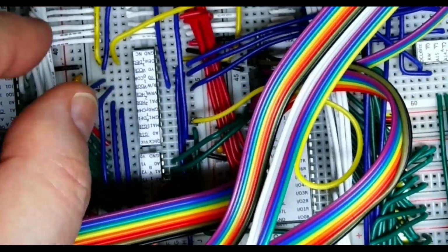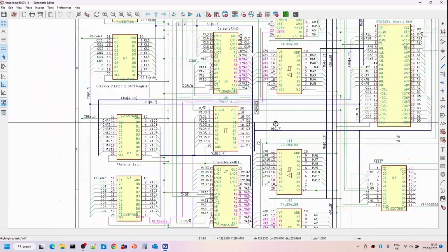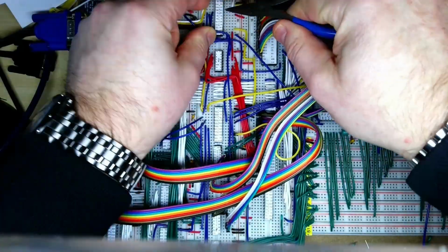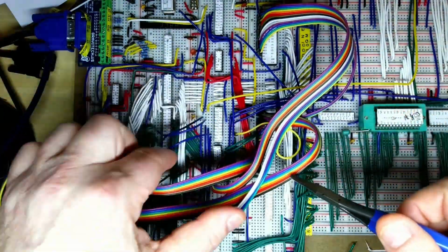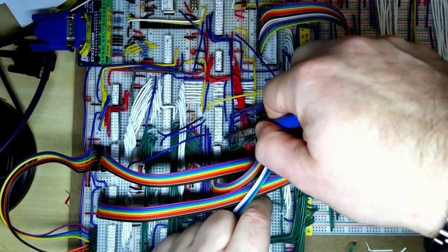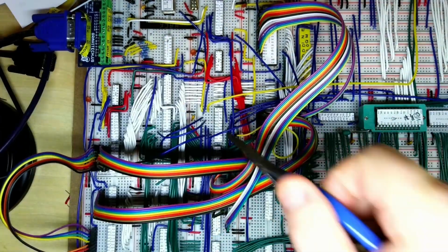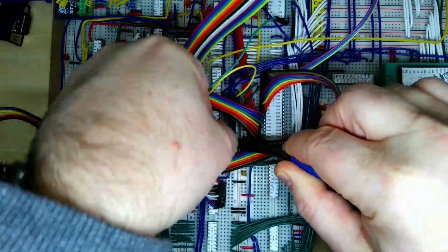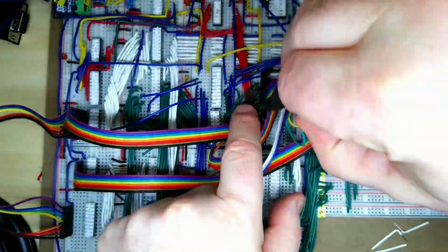We'll need to modify that again, and now we're going to wire in the various control signals, so our graphics mode, page register values, and first of all plugging in the clock divided by 4, the dot clock divided by 4, taking the enable signals out from there to go to the new graphics latch enables, and then that's just wiring in the page address and the graphics mode values there. So this is moving down the CRTC lines to allow for that extra raster address line there.